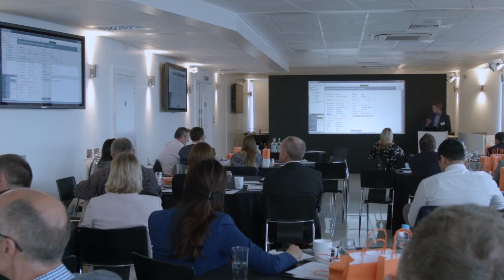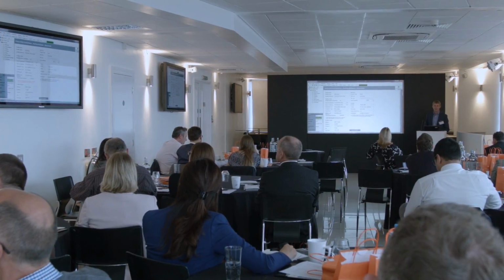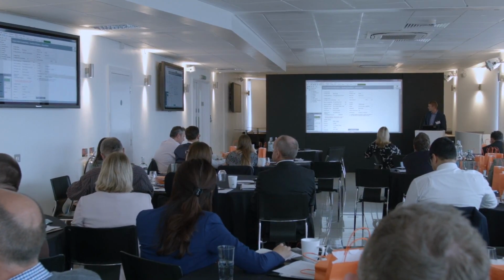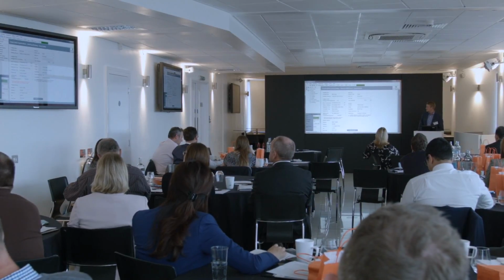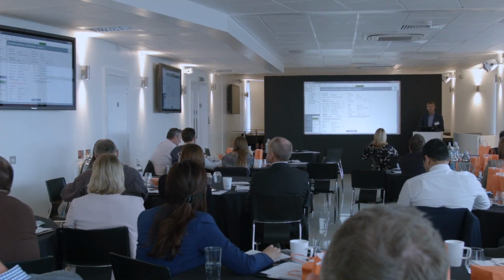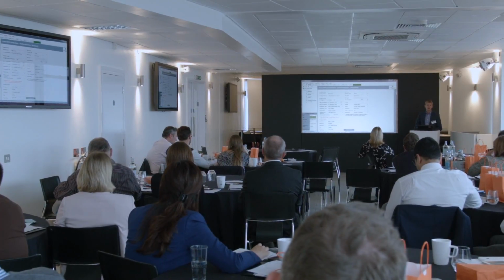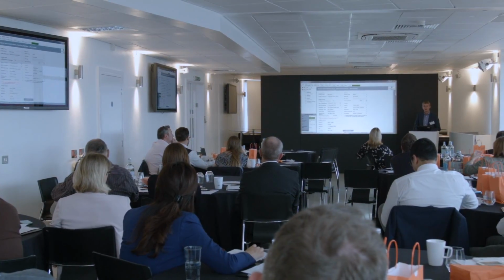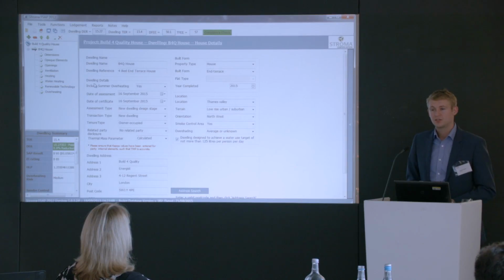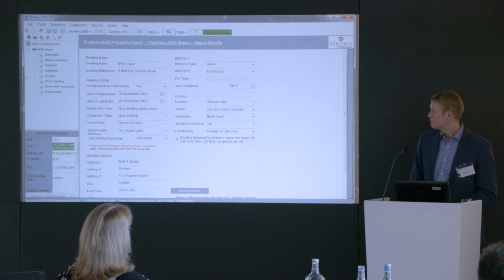So, the first page I won't really go into very much, it's mostly administration. The only thing that will make a difference is the location. So this house is in the Thames Valley. The only areas that influences is summer overheating, and if we had air conditioning or comfort cooling, it would influence that as well. Location in SAP doesn't currently influence your heating demand. That's obviously one area where it could become a bit more accurate in the future.